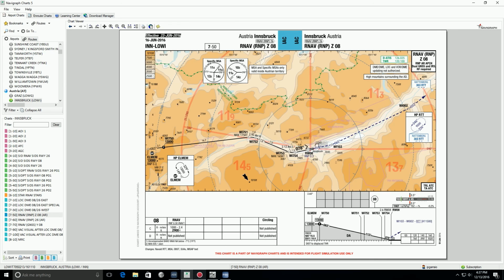In case of go around, what do we have to do? We will fly a LNAV go around, so we will push go around button, TOGA, flaps 15, positive rate gear up, and we will have LNAV, and it will follow the go around to Whiskey India 002 climbing to altitude 11,500 feet, which is down there here.